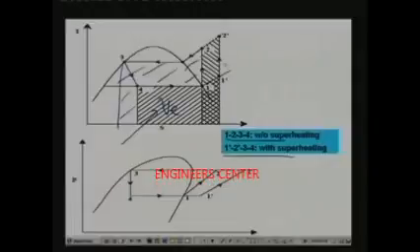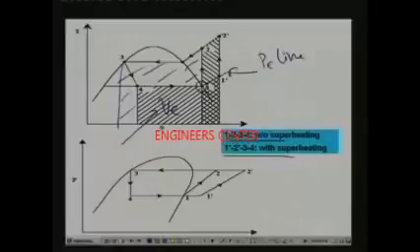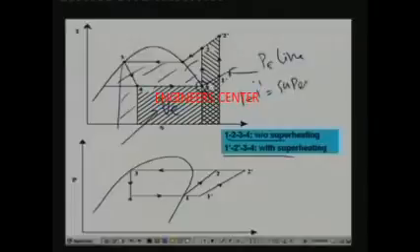Now let us say that I have superheated it. Superheated means what am I doing? I am pushing this exit condition from the saturated vapor to a superheated vapor along the constant pressure line. That means this is the constant PE line. It is a sensible heat transfer process, assuming that there are no pressure drops, so it is taking place isobarically. So this point is shifting to the superheated region. Remember that you have the subcooled region here, two-phase region here, and superheated region here. Because of this superheating, 1 to 1 dash is your superheating.